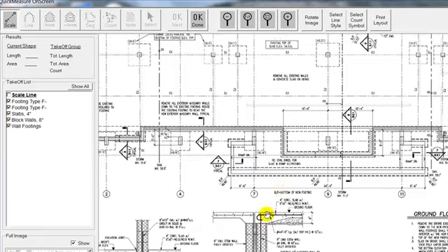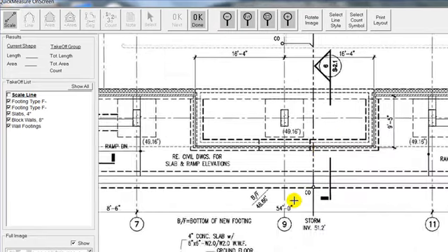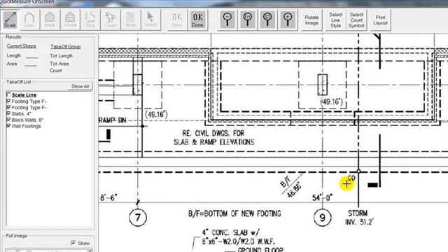Now, you guys out there that have worked with digitizers in the past know that before we do the takeoff, we had to apply a scale to the drawing, and so we do the same thing here with the PDF. We can work on a graphic scale or a dimension line somewhere. If there are no dimensions, we can always use a column line or a doorway somewhere that we can at least apply a scale to it that way.